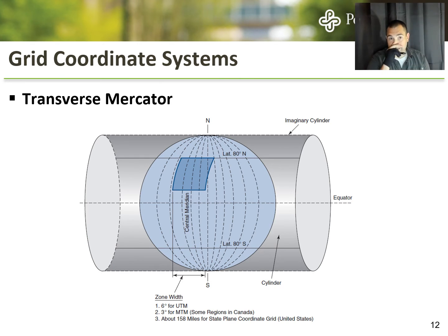Okay, so the other type of state plane coordinate system and grid system more specifically is called a transverse Mercator, which is using a cylinder, just a small portion of a cylinder, to approximate or project features from the surface of the Earth onto that, and then you can cut that cylinder on one side, spread it open, flat, and then get your grid system that way.